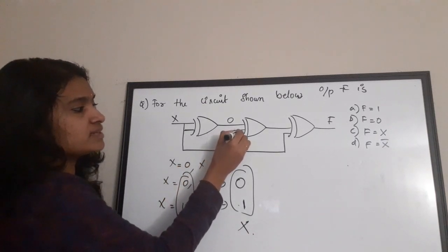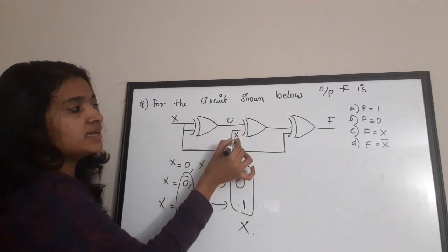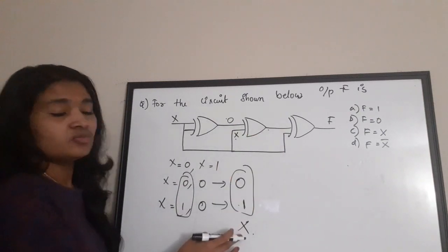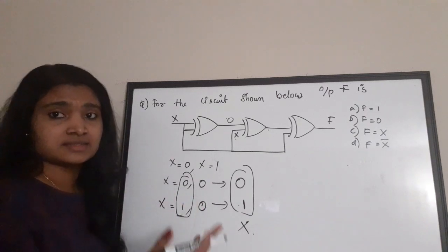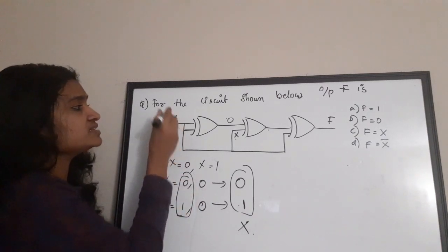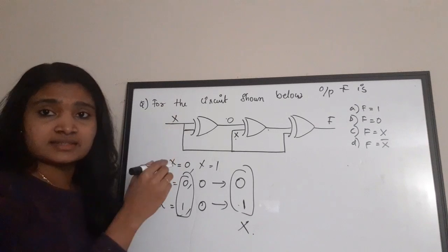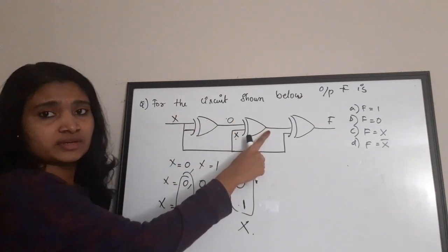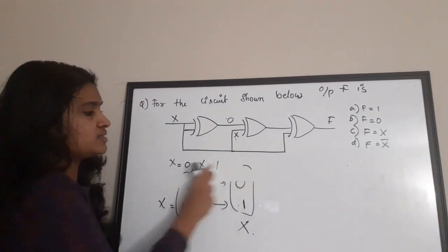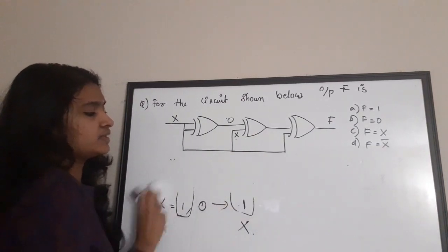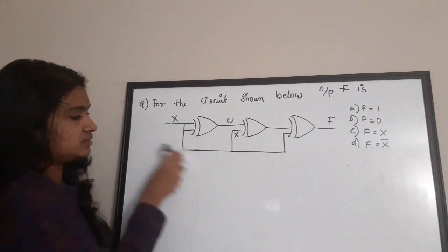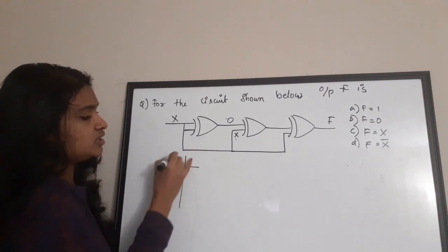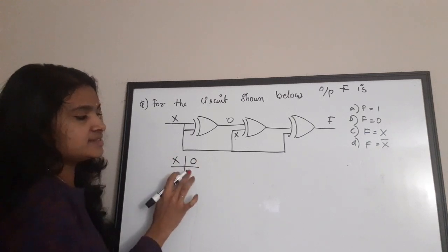Here we are going to XOR 0 and the input X. So, the output of this XOR gate is whatever value is coming as X, that is whatever value we give as the input X, it is going to come as the output of the second XOR gate, right? So, I will explain it once again. See, for the second XOR gate, we are going to fix the input X and we are going to feed a 0.